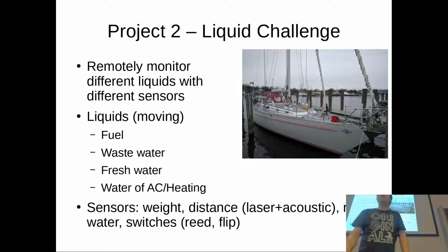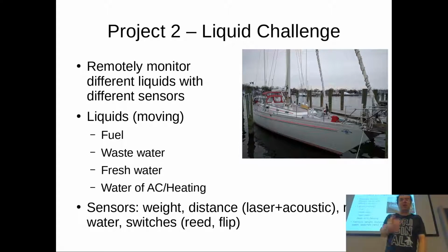Then you want to try various binary devices, which just tell you it's empty or full, based on the reed switch or one of these tilt switches. There are others which click if there's enough weight, or use the Hall sensor with a magnet. So find at least two others where you can do a binary measurement.